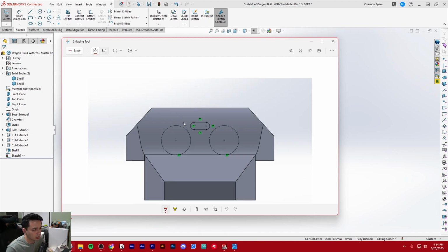So that's the plan. The trick is that we need to build a cylinder that isn't on top of our ultrasonic sensors but goes around it. And then there's going to be this little gap here, right? And whatever this gap is, there has to be a small amount of space so that the ultrasonic sensors can slide into the two cylinders. Because if we make them the exact same diameter, they're not going to fit. It should be very close to the same diameter, but slightly larger, so it leaves a little space for your ultrasonic sensor to slide right in.